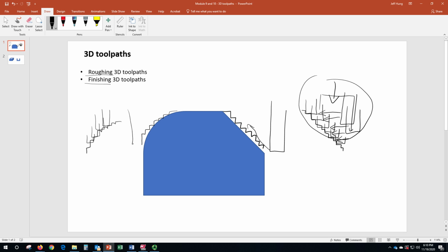I can have my cutting tool over here and move this direction. So I can cut it at once without putting too much load on the cutting tool. So these two right now are called finishing paths because I'm not putting too much load on it. I just cut at the tip. And this one and this one are the roughing cuts.